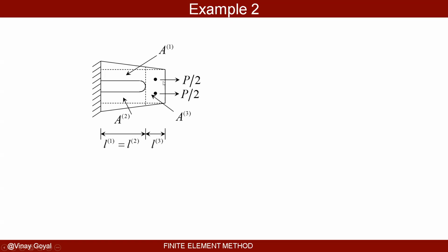I have to figure out a way of idealizing this. The cross section is varying. You can see that there. The cross section here is also varying. And the length here is, as you saw, L1 and L2 and L3. You can see here that I've discretized the domain into maybe say a little rectangle here, and a rectangle here.